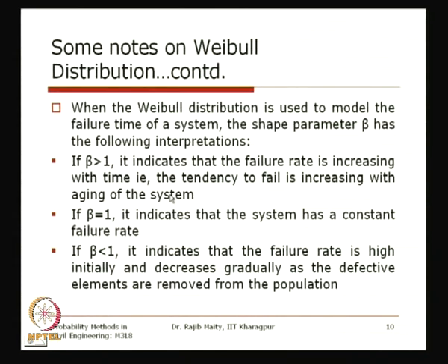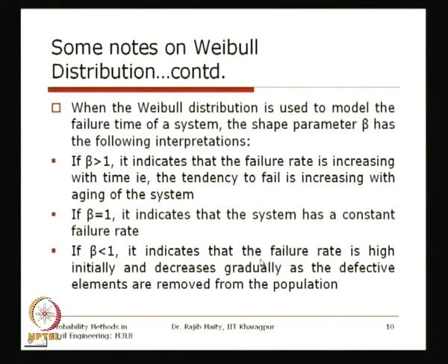For any structure, due to its aging problem, or some apparatus due to its fatigue problem, when time increases, sometimes the interarrival rate of the phenomenon may increase. So, here we are deviating from the basic assumption of the exponential distribution, that the failure rate need not be constant over time from 0 towards plus infinity.